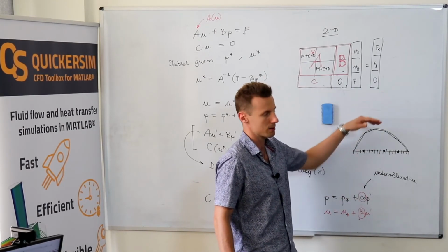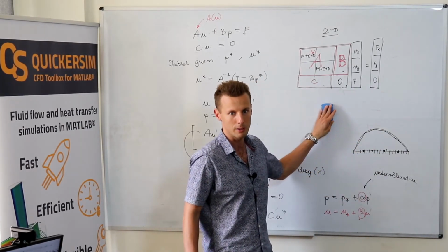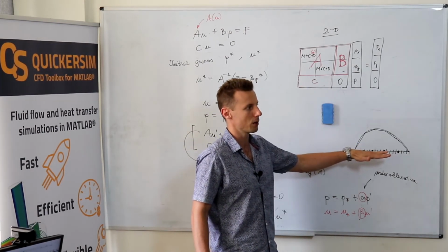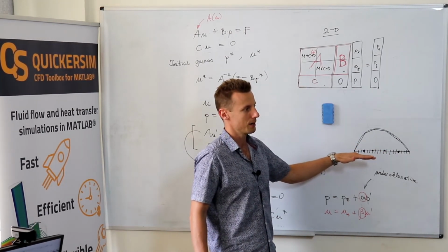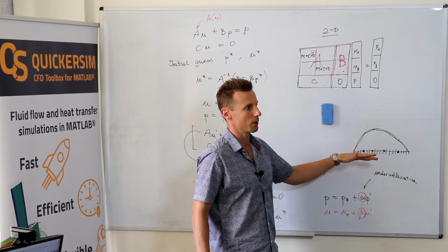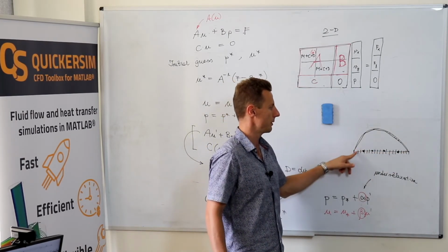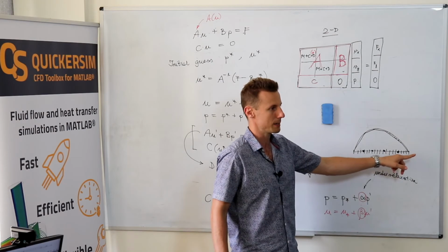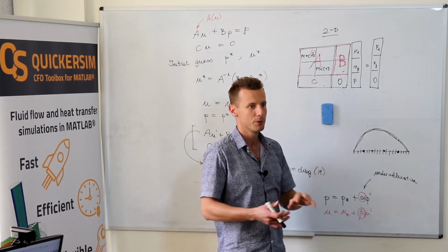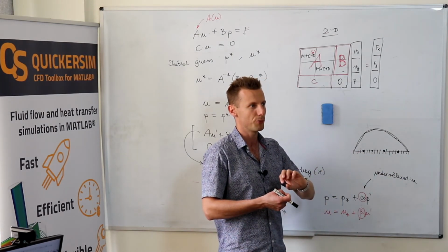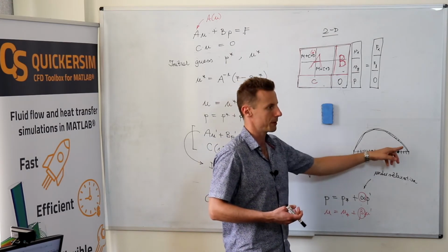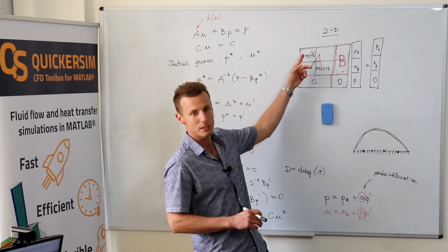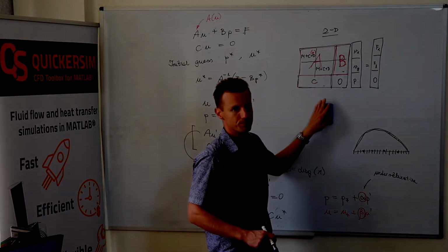But then you need to propagate the solution back to the fine grid, and that's the multigrid concept. The algebraic multigrid is the extension of this concept because you don't need to build the computational mesh explicitly, but algebraic multigrid attempts to figure out these dependencies based on the entries in the matrix.